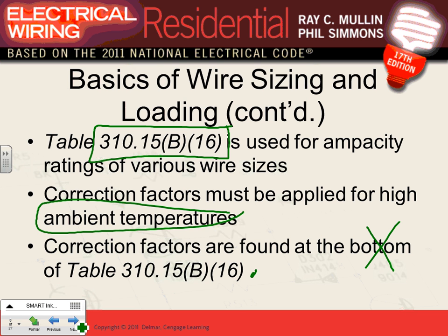That's why the electrical utilities, why do you think they send all these transmission lines overhead? They're naturally cooled, right? They're not trapped. They don't trap the heat. So keep in mind, because of all this heat, we're going to be derating based on ambient temperature. And I know you guys did a little bit of this table, but I would like to walk you through it one more time for the commercial, industrial, and the residential. So keep this in mind for that.